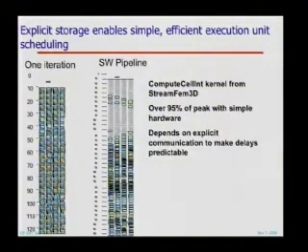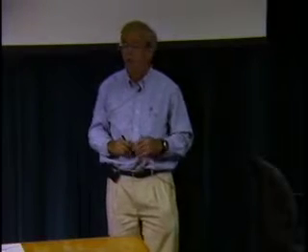And what you see, these are the 4 floating point multiply-add units on Merrimac, is that they're busy nearly every cycle. The occupancy here is over 95%. In contrast, running the same code on a state-of-the-art x86 machine, it sustains something less than 5% of performance. And that's because, even though this code is such that if you stage the memory right, you can get by with the memory bandwidth those machines have, the reactive nature of trying to feed the ALUs and the centralized nature of the structure that's feeding them will not sustain this kind of performance.